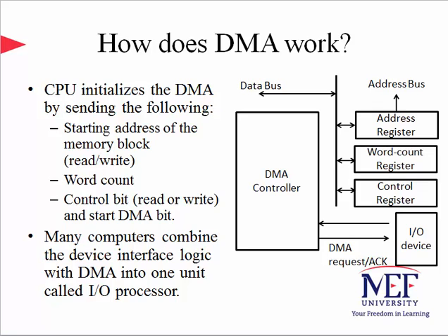When the DMA uses the memory bus, the CPU is temporarily disabled from accessing that bus. As the data moves from peripheral to memory or vice versa, the word count decrements and the address register increments to point to the next memory location to continue the transfer. When the count hits 0, it means the DMA has completed transferring. The DMA controller raises an interrupt, and the operating system therefore knows the transfer is complete and switches back to the old process and continues its execution.